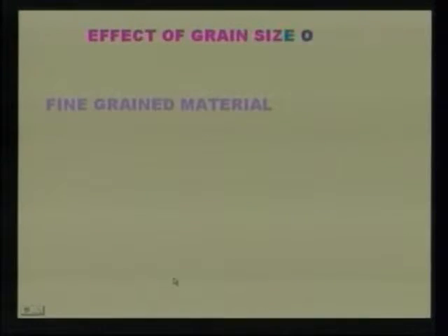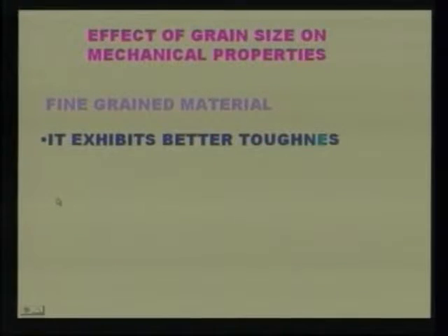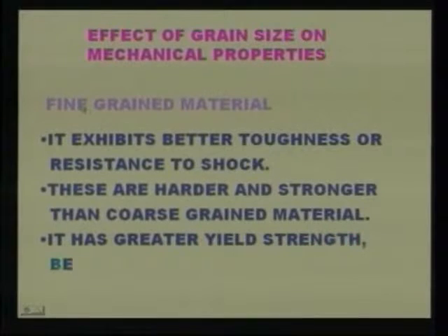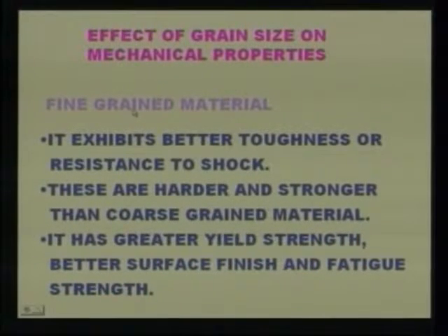Now let us see another effect, the effect of grain size on mechanical properties. Let us discuss the fine grained material first. In fine grained material, it exhibits better toughness or resistance to shock. This is an advantage. These are harder and stronger than coarse grained material. It has greater yield strength, better surface finish and fatigue strength.